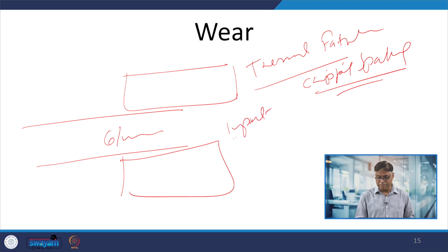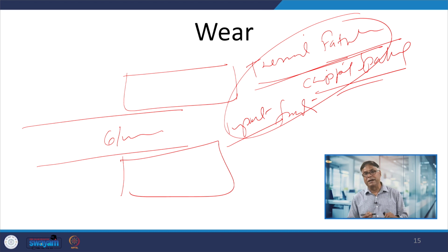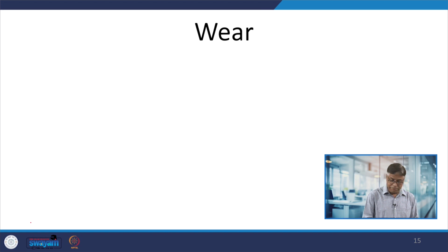So, impact fracture and thermal fatigue related damage, these two types of damage make the guides unrepairable. If the guide has been damaged due to continuous thermal fatigue and impact conditions where fracture has taken place, and cracks have nucleated due to thermal fatigue, they make the guides unrepairable. And we need to replace them.